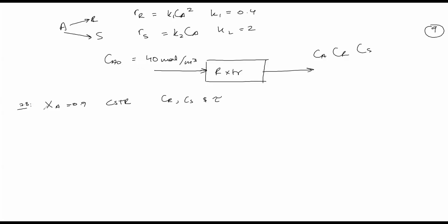And there are two ways to do it. You could use the selectivity, or, what did we call it? Let me recall the exact term we used. You could use the fractional yield, which is the expression we introduced during lecture 7. And I highly recommend you use the fractional yield. It makes the algebra slightly easier when doing these problems.